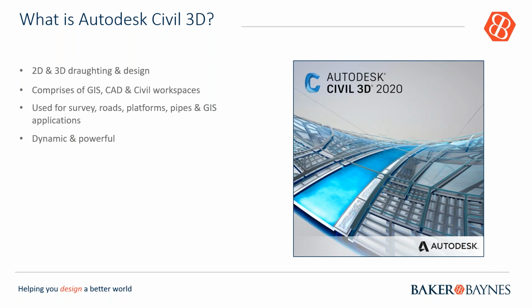So it's very detailed. What makes it very powerful or very popular with the designers, including myself, is its dynamic and powerful interface. So a lot of old software, or well, I think they are actually upgrading them now, hopefully, fingers crossed, but there wasn't a dynamic component incorporated into the software, meaning that if you made any changes to a certain elevation or to a road alignment, if you increased or decreased the vertical alignment height, or horizontal alignments or platform elevations, for example, the cut and fill values wouldn't update, the long sections wouldn't update. You have to go and physically manually either redo it or alternatively manually refresh it.